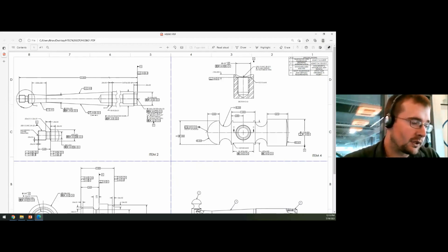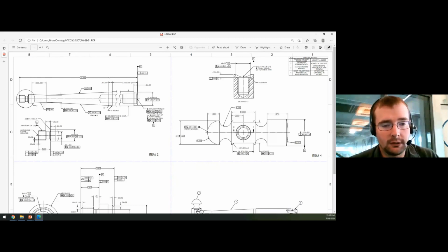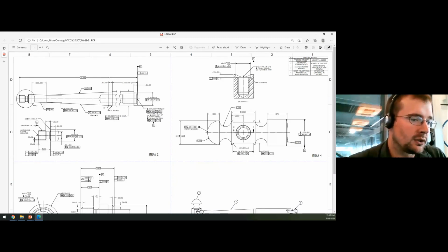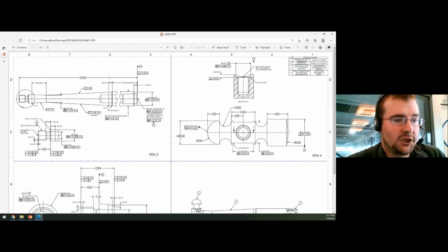A lot of the conversations that come up are, why is this tight of tolerance? As a machinist, that's not necessarily the call you have to make unless you're maybe in a prototype environment. You have to make the part. You're assuming that the part was quoted given the said tolerances, and you need to achieve that, so that the tolerances hopefully dictate the machining operations.